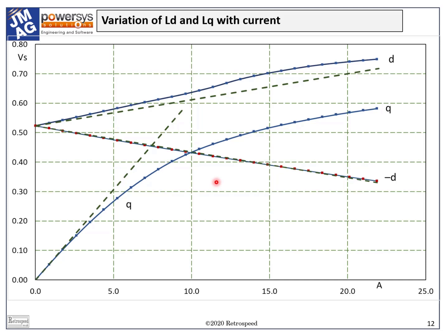In fact, we will have a closed-loop control that generates a current demand signal, just as we saw in the induction motor controller earlier. But we also need to know that the inverter has enough voltage available to drive this current. So that is why the voltage calculation is important.